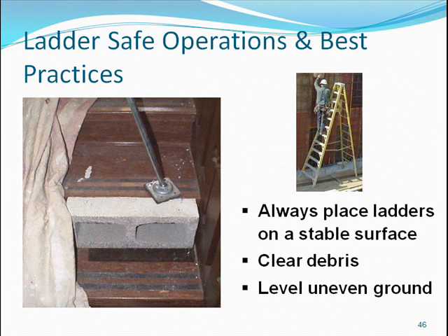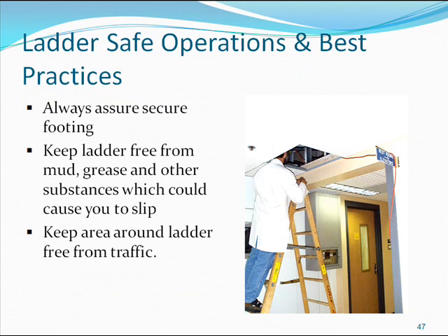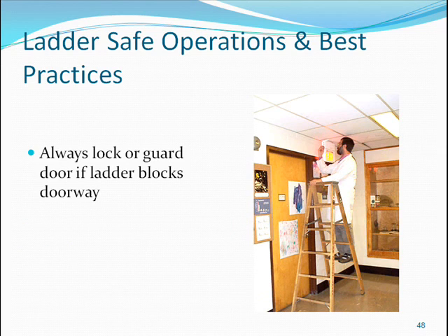Ladder safe operations and best practices. Always place ladders on a stable surface. Clear debris, level uneven ground. Always ensure secure footing. Keep the ladder free from mud, grease, and any other substance which can cause you to slip. Keep the area around the ladder free from traffic. Always lock or guard the door if the ladder blocks the doorway.